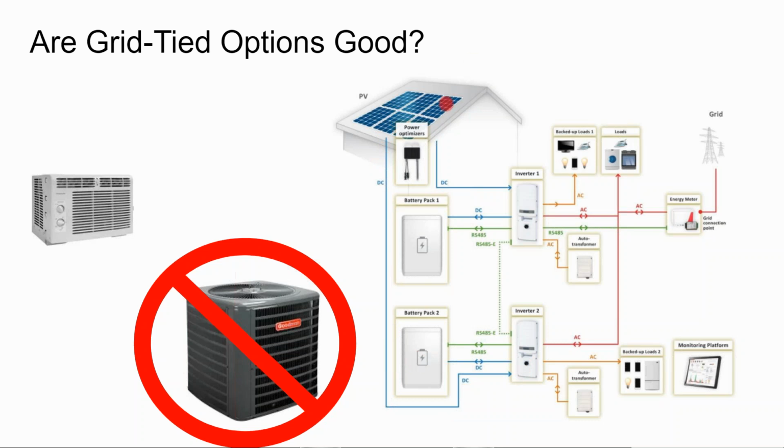And so you have your solar, you have your battery. These are grid connected inverters, so you can still outflow to the grid and sell back. Maybe you have net metering and you get a good rate for that. If you don't have net metering, you can use the lithium ion battery to keep your energy. As we learned earlier, the economics are kind of where you're just spinning your wheels. You're spending money on batteries, you're not spending money on your electric bill so much, but it's a wash on whether or not that's economic. But the customer really wants the battery because if the power goes out, they want to use their solar array.